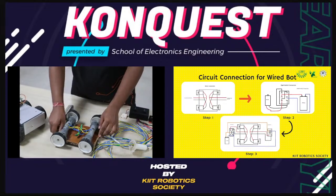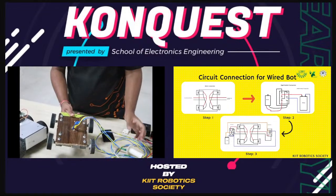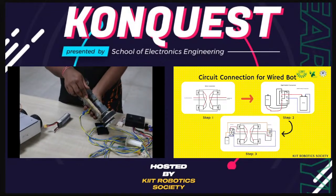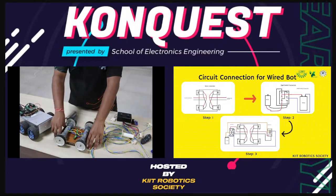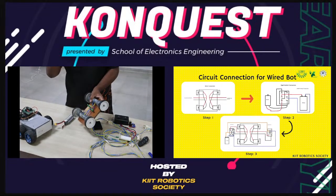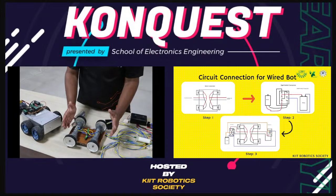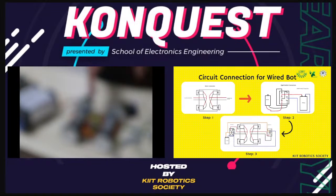This is a kind of wired bot, which is from the Robotics Society only. Now, how is it made? So this is the chassis which we have made using plywood, actually it's wood. These are the L clamps, shaped to hold the motors upon. We used screws to tie them. Now see the alignment, the motors are parallelly aligned in the chassis.